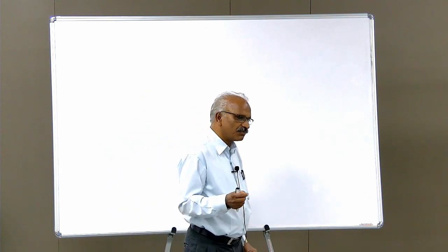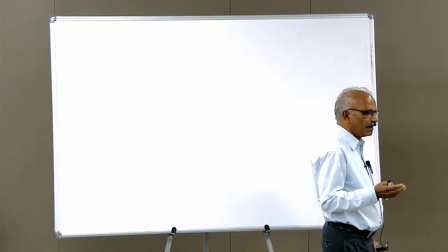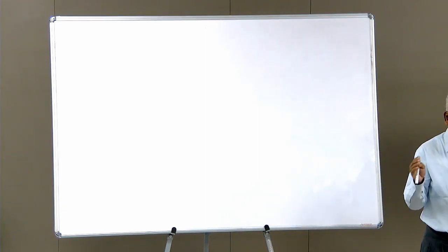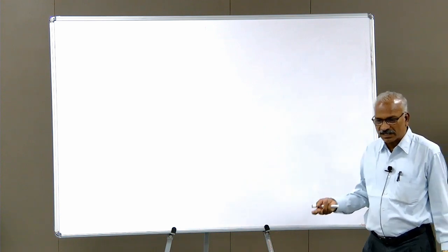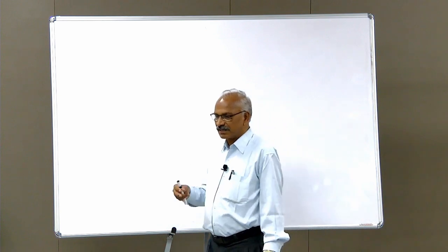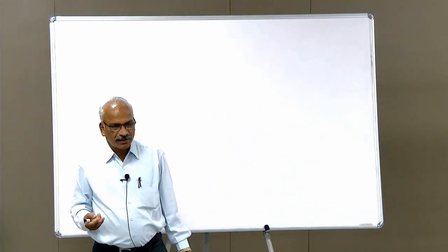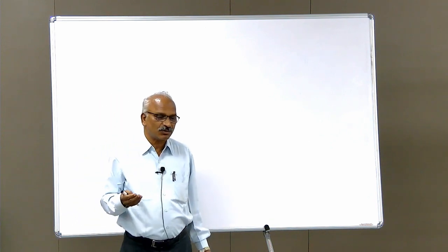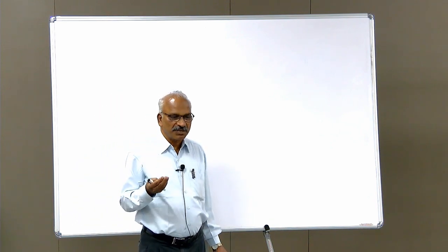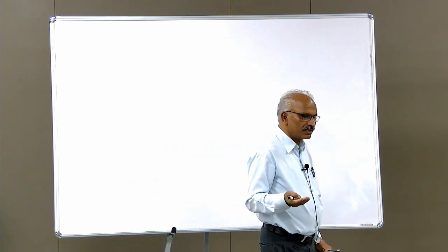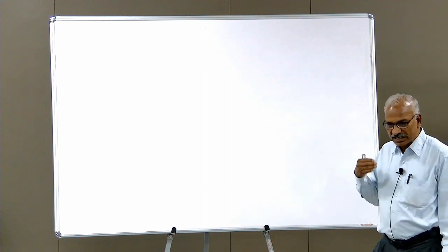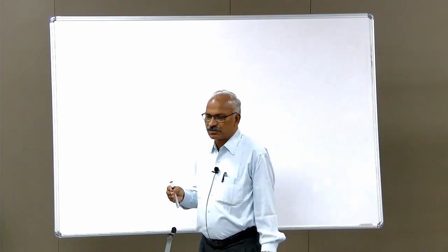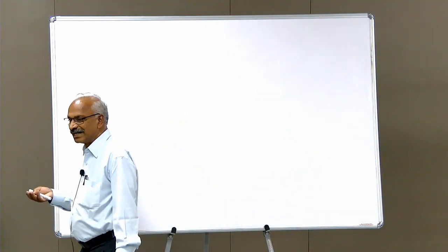So it is the duty of the structural analyst to find out the bending moment and shear force. For that, one must have knowledge about how the load gets transferred to the structure, whether the load is acting as a point load, or UDL, or uniformly varying load. One has to be familiar. Then, when it is subjected to loading, how the structure behaves, whether it is going to behave as a cantilever, a simply supported beam or slab, a continuous beam or slab, one must be familiar. After knowing the loading pattern and the behavior of the structure, which is very important, we can find out the internal forces and also the displacements.